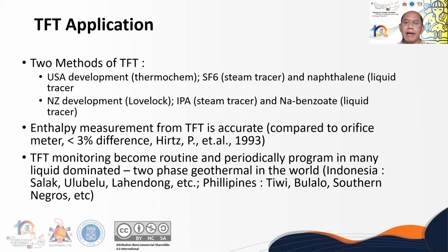Two methods of TFT are recognized. The first one, developed in the US by Thermochem, basically uses SF6 as steam tracer and a kind of naphthalene as the liquid tracer. The second method, developed in New Zealand by Brian Lovelock, uses isopropanol as steam tracer and sodium benzoate as a liquid tracer.